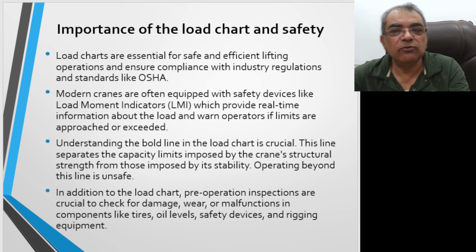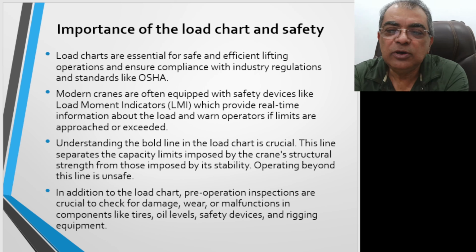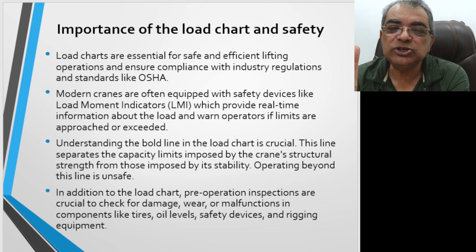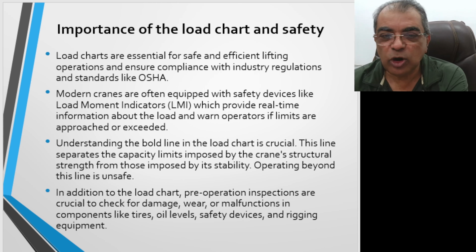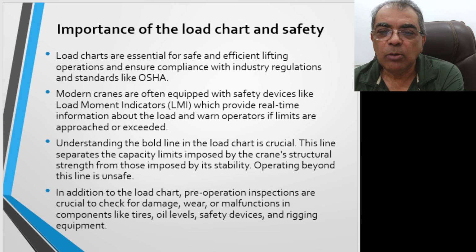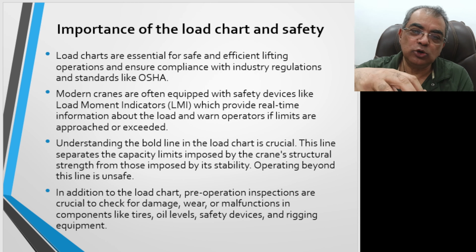Importance of the load chart. What is the importance of the load chart and safety? Load charts are essential for safe and efficient lifting operations and ensuring compliance with industrial regulations and standards. So whenever you are preparing a lifting plan or anything regarding lifting, you always have to refer to the load chart. Modern cranes are often equipped, as I have told you, with a device like a load moment indicator. Okay.